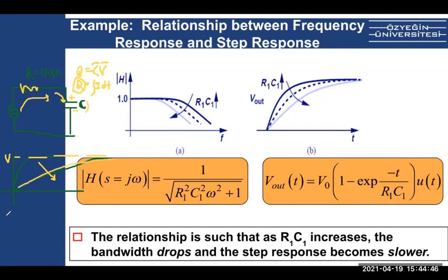And if you remember from the time constant, if you write the mathematical equation of this cap, VC will be, let's call it V source, V source times (1 minus exponential of minus t over RC). Okay? The RC here was our time constant, if you remember. Therefore, the smaller this RC is, the faster the circuit will charge or discharge.